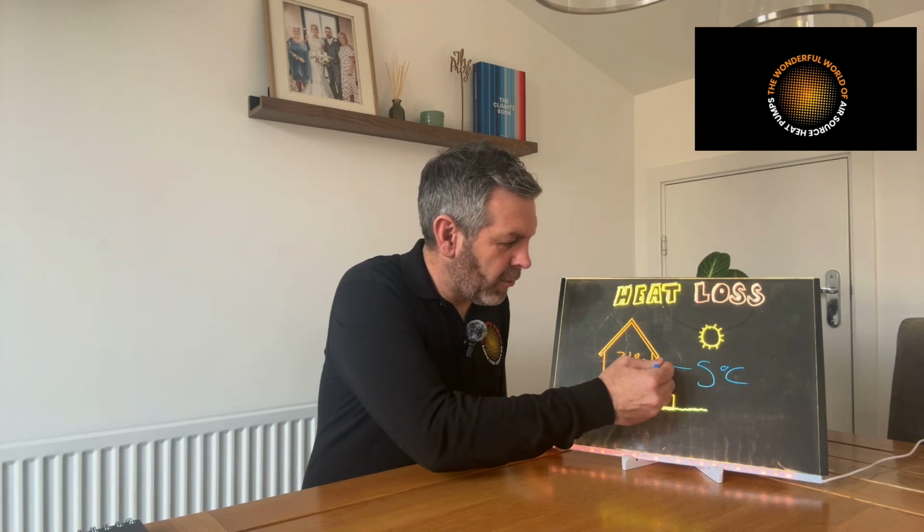So what our heat loss calculation will do, it will calculate the energy that we need when it's -5 degrees outside to maintain an indoor temperature that is comfortable and is 21 degrees. Because if you remember from the thermodynamics that we covered and in the video, we will always have movement of thermal energy. And when it's 21 degrees indoors and -5 outdoors, our thermal energy will move one way, from indoors to outdoors. And what our heat pump has to do is match that energy to maintain that indoor comfortable temperature.